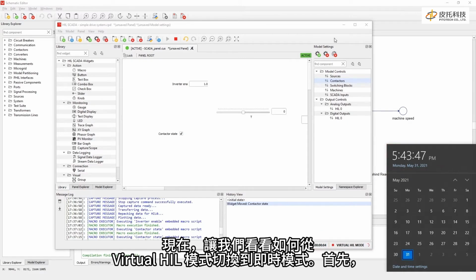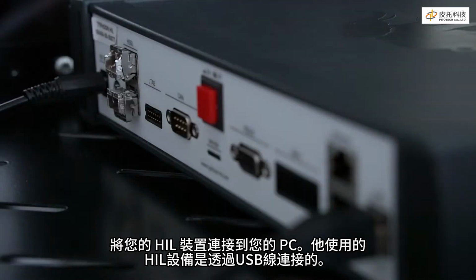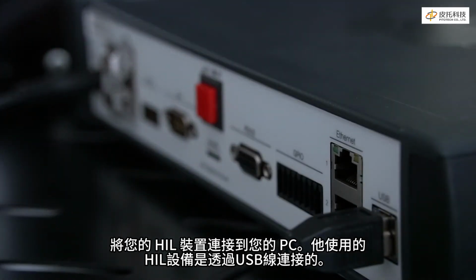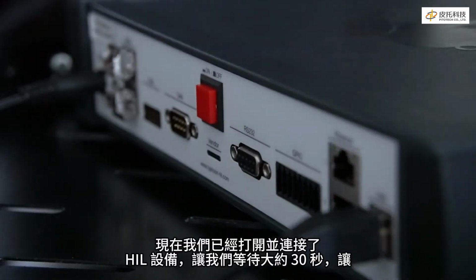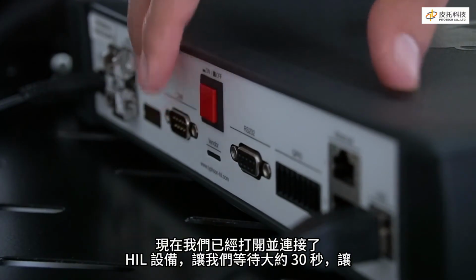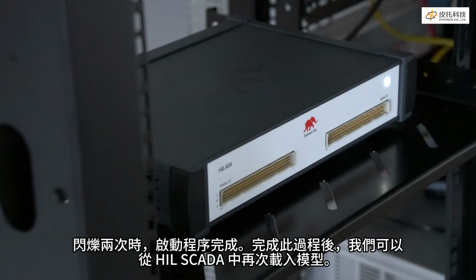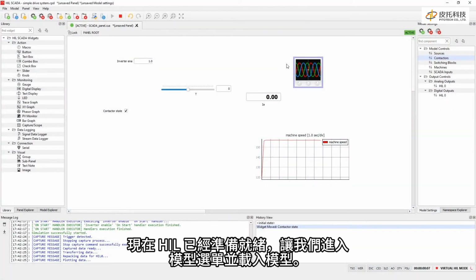Now, let's see how we can switch from Virtual HIL mode to real-time mode. First, connect your HIL device to your PC. This particular HIL device is connected using a USB cable. Now that we have turned on and connected the HIL device, let's wait around 30 seconds for the HIL device to boot. The process of booting is finished when the LED on the front plate of the HIL blinks twice. After this process, we can load the model again from within HIL SCADA. Now that the HIL is ready, let's go to the model menu and load the model.